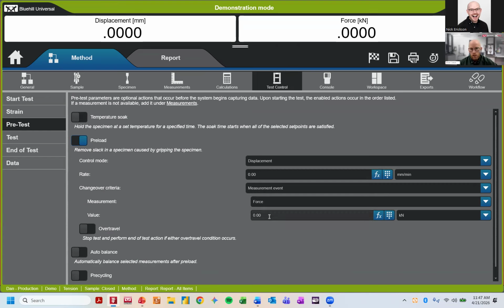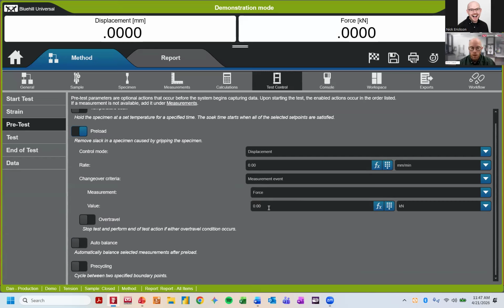And then if you do clamp your specimen, you get a little compression on it. You want to pull it to some level of force, that of course you're not balancing the force out. So you're always going to maintain that true force on the material, but you just want to make sure it's not too high because data collection hasn't started yet. Okay,